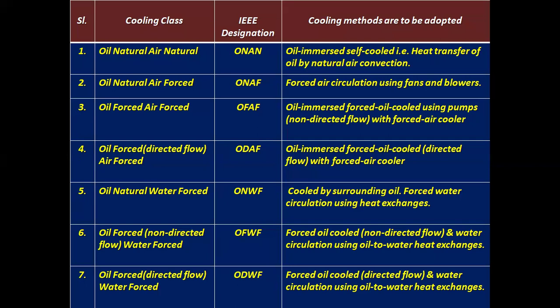Non-directed flow with forced air cooler. Oil forced directed flow, air forced, that is ODAF. Oil immersed, forced oil cooled, directed flow with forced air cooler. Oil natural, water forced, ONWF. Cooled by surrounding oil, forced water circulation using through heat exchangers.